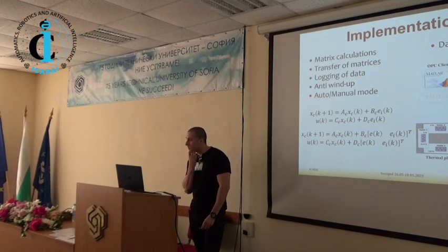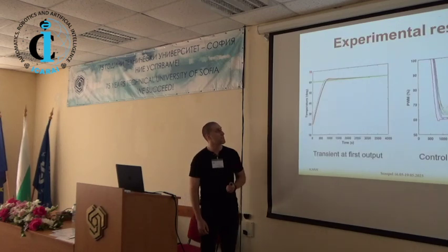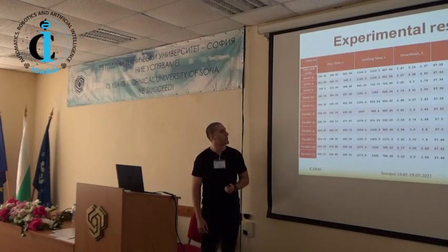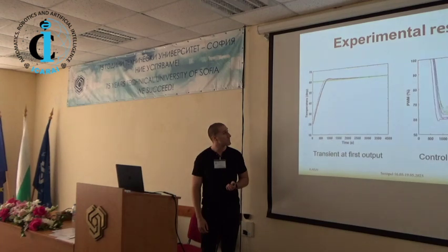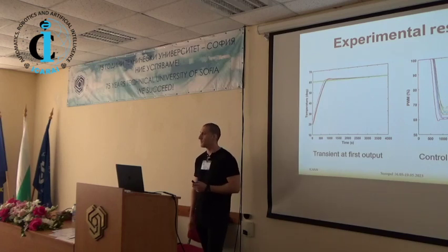One of the main issues in model reduction in closed loop is what to do: first reduce the order of the model and then design the controller, or use the full order model, design a controller, and then reduce the order of the controller. As I understand, you are applying the second approach. You have a high order model, 18th order, design a controller, and then reduce.